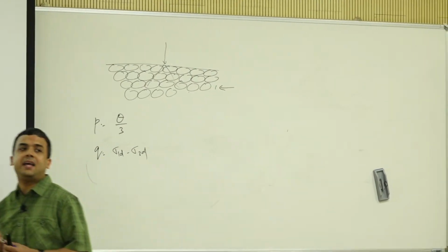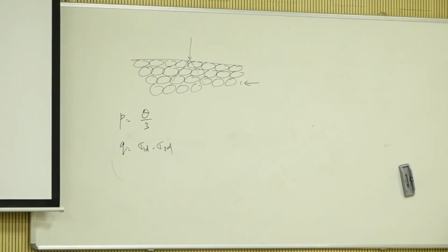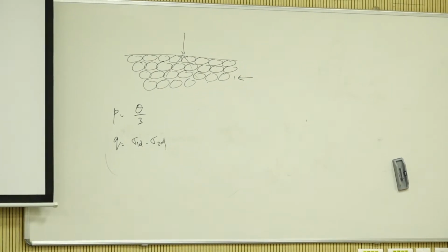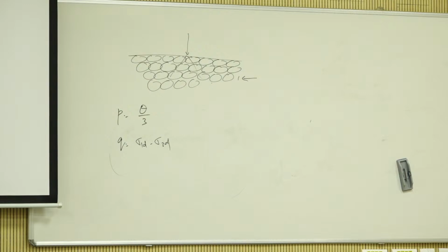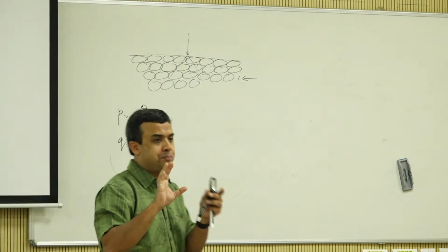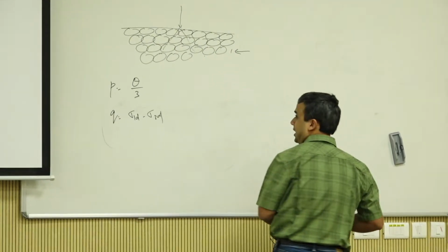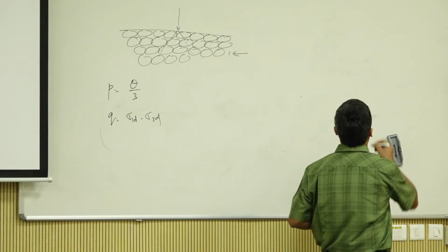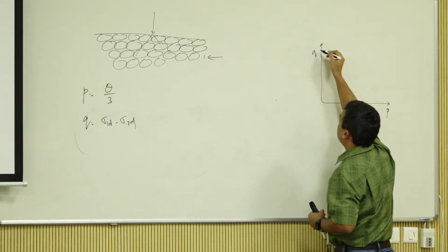Okay. Why is this important? What is stress path? Those of you who have taken advanced geotech classes know that stress paths are almost like a health history of the soil. You can see how it is being loaded and what stress it is experiencing, and you can plot it on a PQ plot. So the x-axis is P and the y-axis is Q.